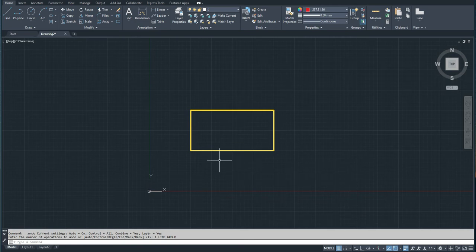And we learned how we can choose the absolute by typing the coordinates in x and y direction. And we learned together how we can draw lines using the relative coordinate systems, the difference between the relative and the absolute: in the absolute, each point is referenced by the world coordinate system, while in the relative one, each point is referenced from the previous one.